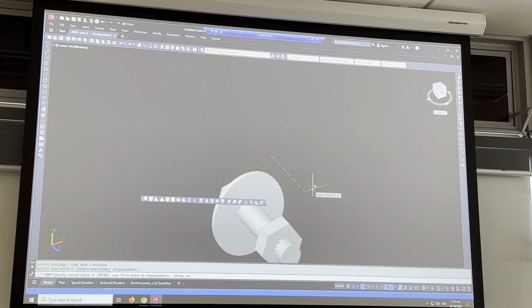So what you have to do is go into the viewport, go view, 3D views, oops, view, 3D views, isometric, so that gets it back looking a bit more like that. And then while you're in the viewport, view, visual styles, and then of course change it to sketchy.